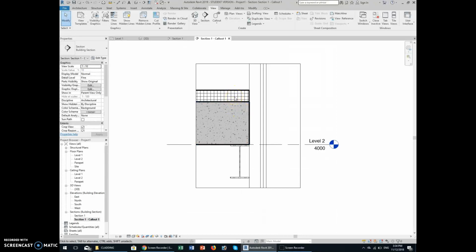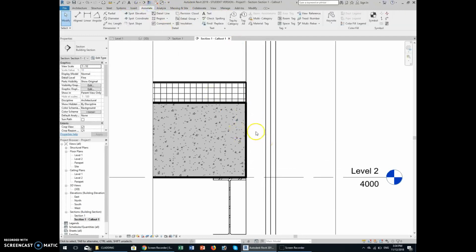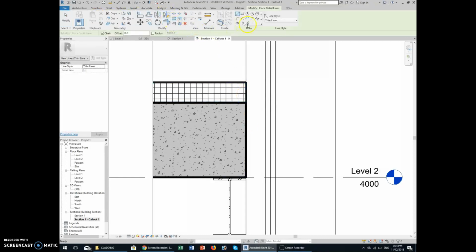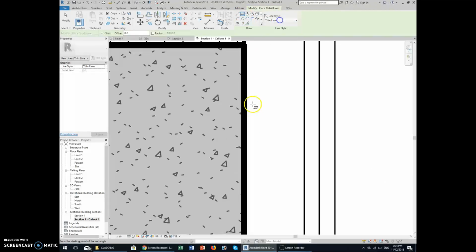Then I want to connect any other element. Here, a metal U. So I'm going to go to annotate, and let's say that this cladding, this curtain wall is connected by a metal U. So I'm going to go to lines, thin line, and I'm going to create my profile. 20 centi is too much, so 1 centi by 15 centi.